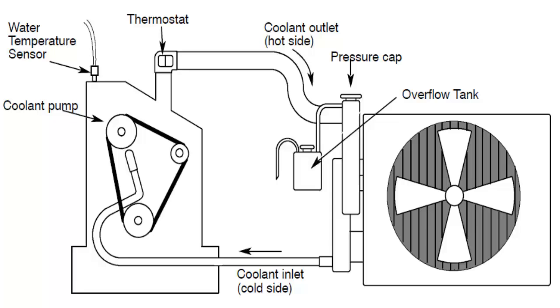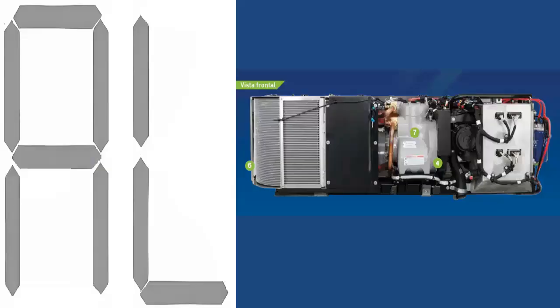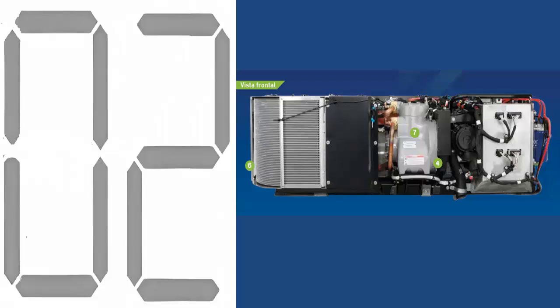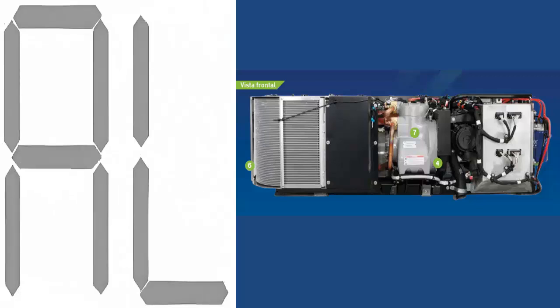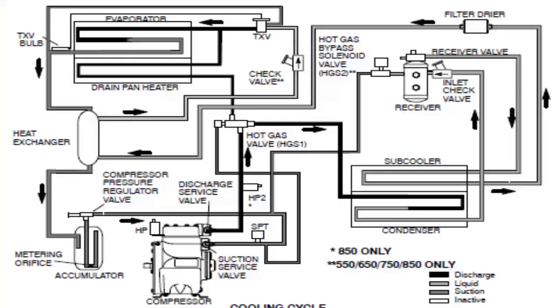3. High pressure in the refrigeration system. This fault is identified with code AL2 and may be caused by obstructions in the condenser's airflow, excessive refrigerant, or compressor issues. It is recommended to check the condenser's cleanliness and verify the refrigerant gas charge.